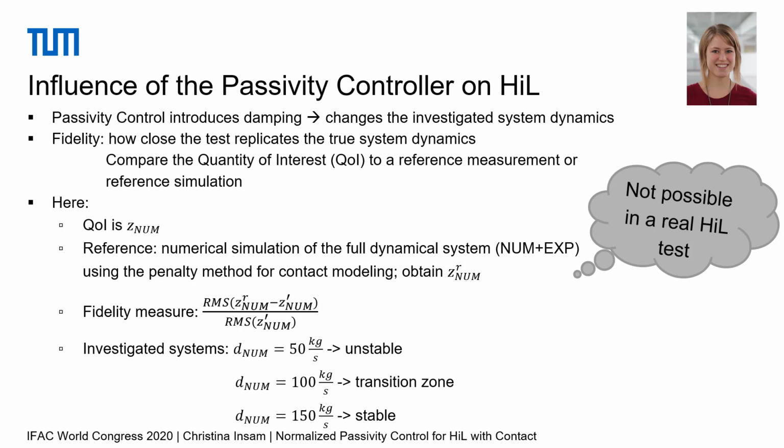The small damping value of 50 kilograms per second corresponds to the videos that I showed before, and you could see that the hardware-in-the-loop test is unstable. For 150 kilograms per second, the hardware-in-the-loop test is stable.